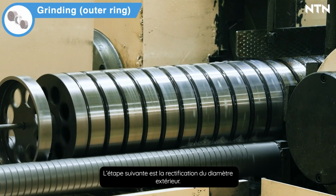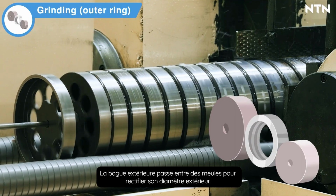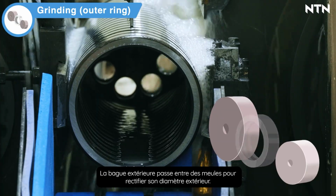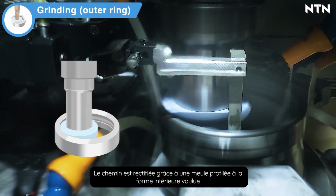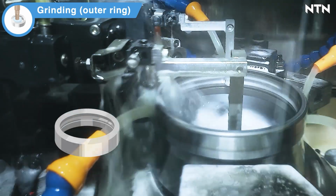The next step is outer diameter grinding. The outer ring is passed through the grinding wheel and the regulating wheel to grind the outer diameter. Next is raceway grinding. The outer ring is ground using a grinding wheel shaped to match the raceway of the outer ring.